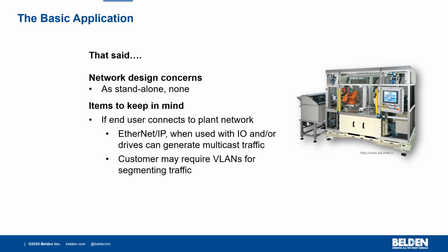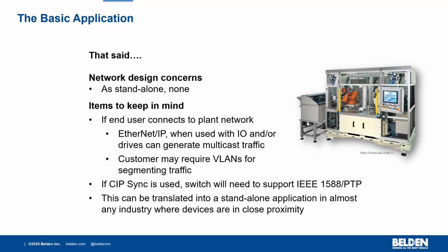There's also an issue of IP addresses. Are these IP addresses already being utilized? And this is where NATing comes into play, and so on. Additionally, time sync. If this is being utilized, you will need to have a switch that supports IEEE 1588. And this can be translated into a standalone application in almost any industry where devices are used in close proximity.